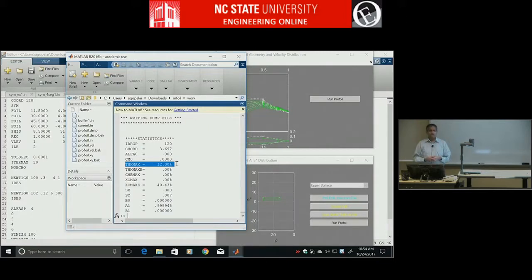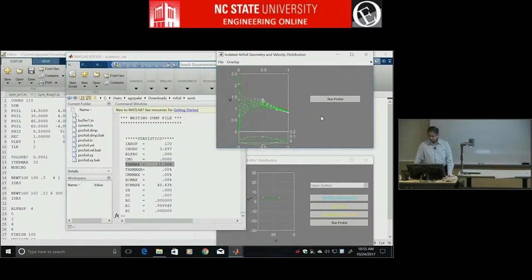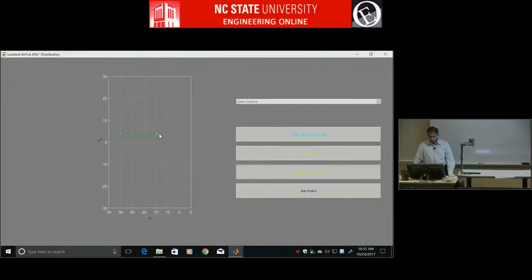Now with the multi-dimensional Newton iteration, you're saying, go fiddle around with all these knobs, do whatever is needed, give me this thickness, give me this camber, give me something else, give me this and give me that. And if it converges, it'll give you all of those things, which is really what you want a computer to do. You don't want to be doing those things by hand. So it figured out that alpha star has to change by some amount, and we can see what amount here.